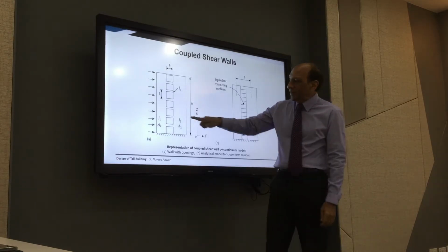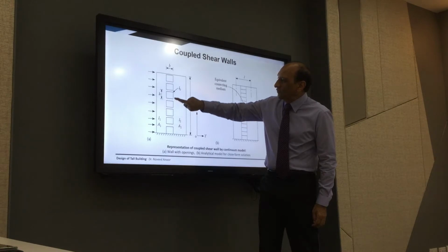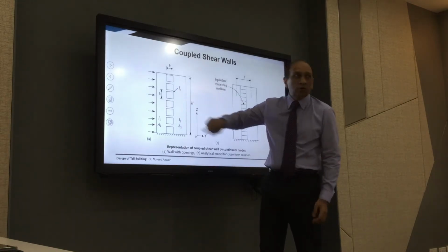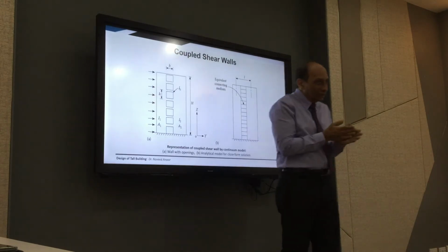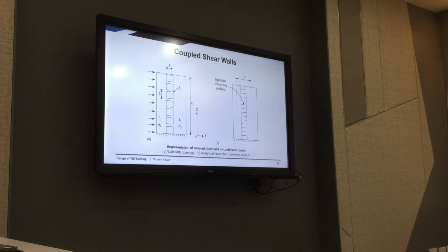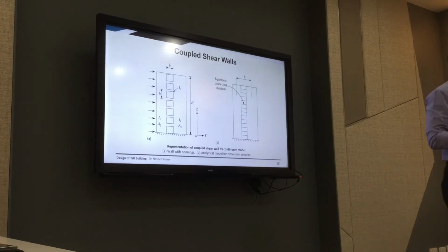You tell them, okay, I can give you lots of space on all the floors, but give me 1 or 2 floors where I can increase the thickness, and you can put the door somewhere else. Or just give me one location where I can put a big beam and I can give you all the other floors free. Like that. So you can bargain with the architects on these things.